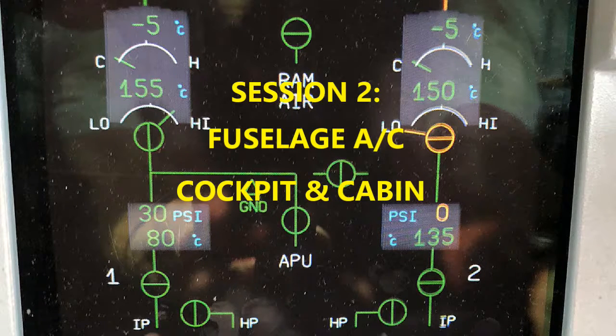There's the plenum diffuser. The other little aspect to the air cycle machine is it has a de-icing system. So that might be a test question. Just know, does it have a de-icing system? Yes, it does. Okay, so you have high pressure air that's coming from the compressor scroll through a duct, and then that circulates through the turbine outlet to prevent the ice formation. Okay, that's how that works.